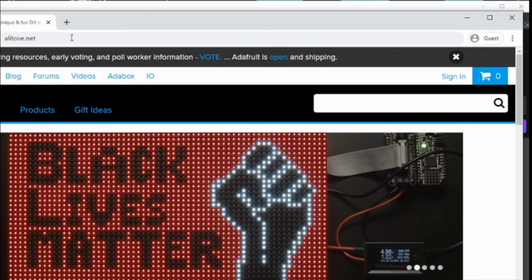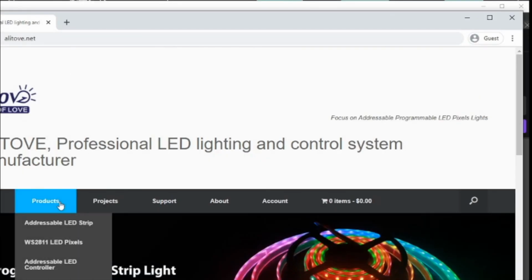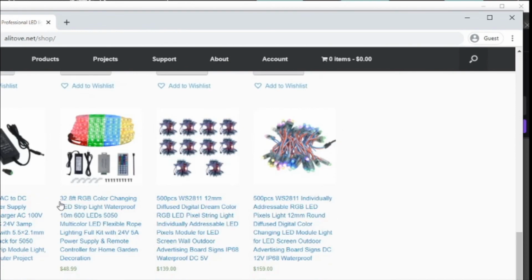Next, I'll look up a couple of candidates of each type. Useful sites include Adafruit, AliExpress, Super Bright LEDs, or eBay. Make sure your lights are controllable using FastLED. Many LED strips are not RGB controllable at all, or use the DMX protocol. I recommend sticking with APA102s or the WS281x family, but there's a convenient list of recommended protocols for FastLED here that will update as time goes on.